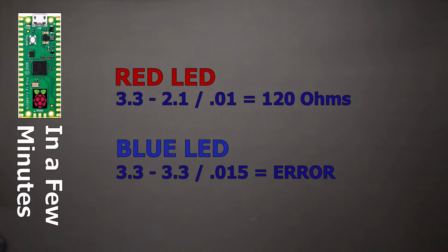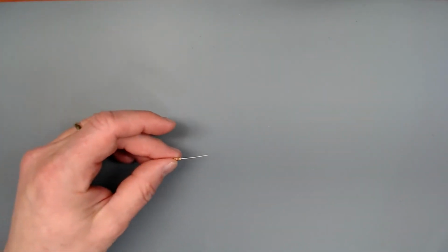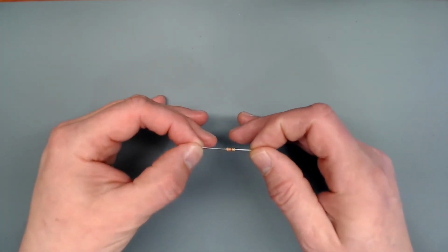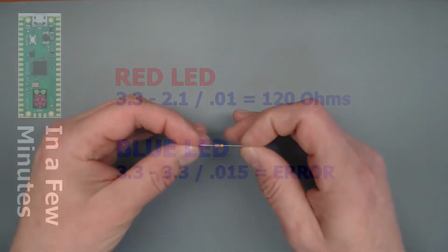Now, for the red LED example, it would have been 3.3 volts minus 2.1 volts of forward voltage of the LED. Divide that by the current in amps, 0.01, which is 10 milliamps, and that would equal 120 ohms. So let me grab a 120 ohm resistor, and I'll try to get that in front of the camera here. And that would be your 120 ohm resistor. The colors are brown, red, brown.